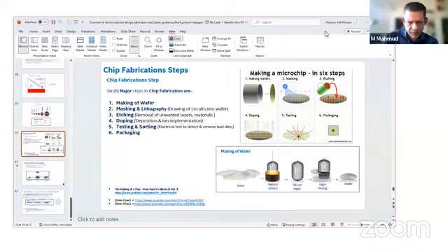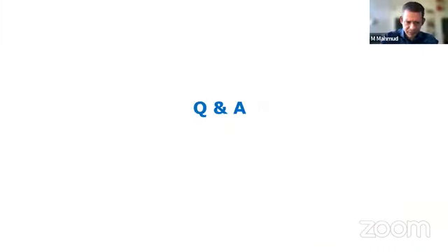One other question, feel free to jump in, especially the process guys. Does technology node actually refer to the channel length? I have seen some PDKs that say it's 90 nanometer tech, but the minimum channel length available is 180 nanometer. Anybody want to take it? I can take it. Yeah, sure. Okay, so when you talk about 90 nanometer tech or 7 nanometer tech, it's the minimum feature size. So channel length does not equate to the tech node.